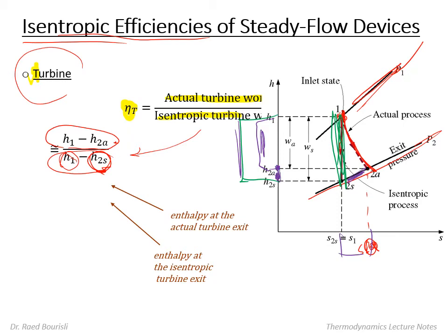It will be lower, and all of the energy will be converted to useful work. However, the actual turbine will not do this. It will translate some of this kinetic and some of this enthalpy difference into useful work output, and a small amount, I hope, into heat irreversibilities.